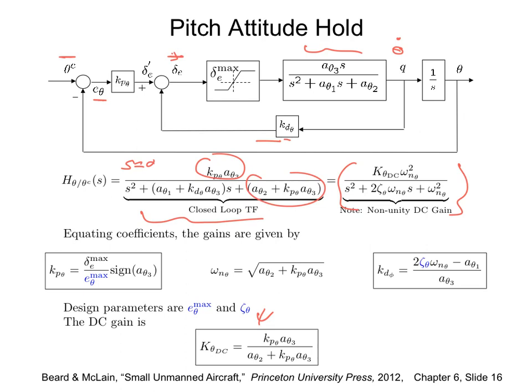Again, to choose Kp theta, we have the same approach so that this doesn't settle. The only thing is this is different here. Basically, the idea is you sign this to avoid that, because the sign of A3 theta is negative, and because of that Kp theta should be of the opposite sign of A3 theta.